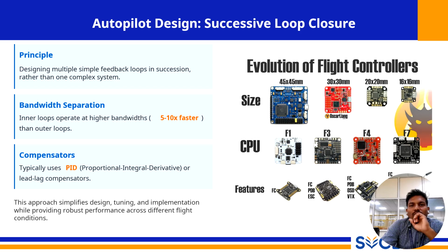The building blocks of each of these individual loops are known as compensators. A flight controller typically uses PID or lead-lag compensators. PID controllers are the workhorse of the control world. They calculate a control output based on the current error, the accumulation of past errors, and the predicted future error, allowing for a remarkable balance of responsiveness and stability.